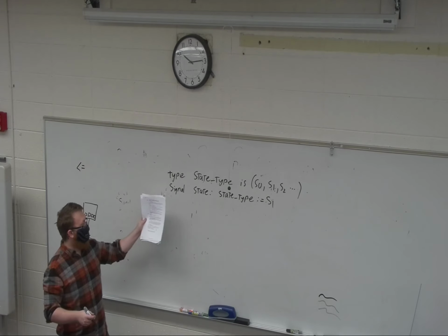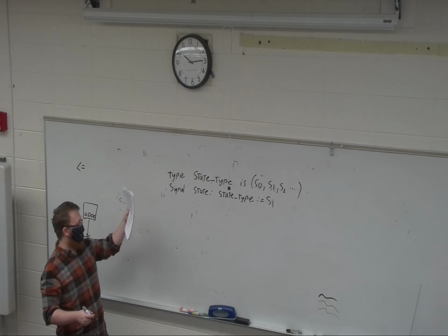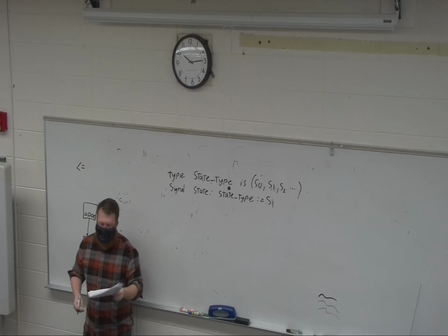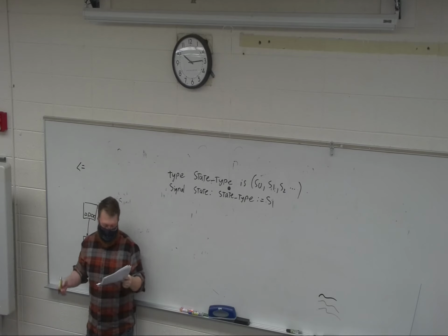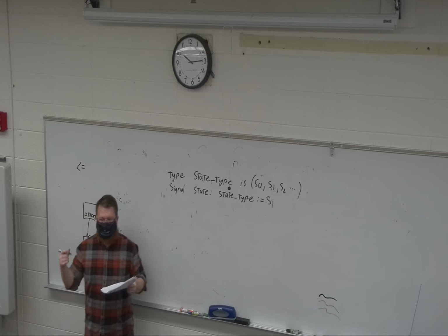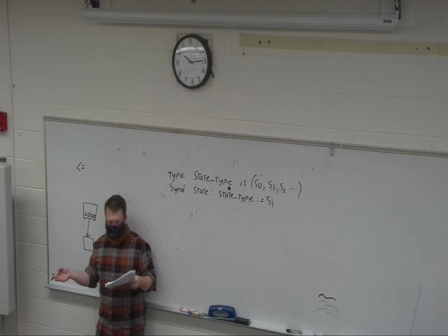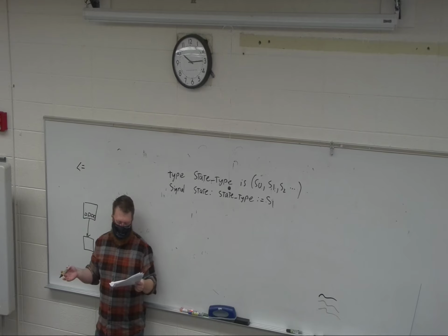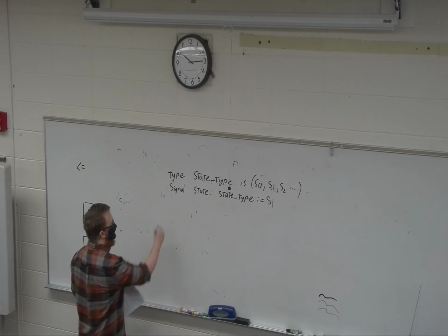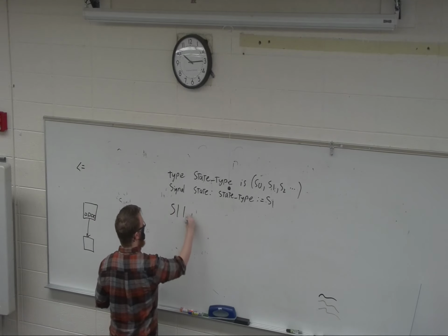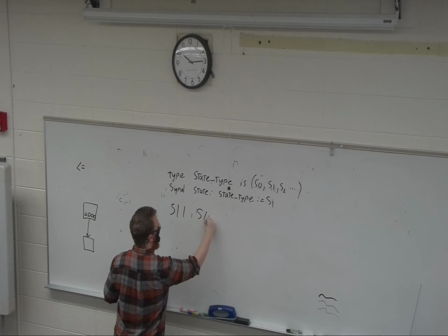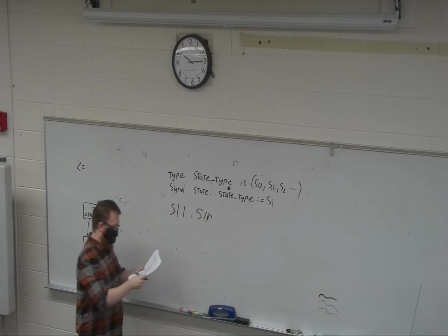I'll circle back around to that after I mention that on page 82, at the bottom, is also a list of VHDL operators that you can use, which are AND, OR, NAND, NOR, XOR, right? That's the binary logical operators. Relational operators, which are equal, not equal, greater than, less than. Shift operators, SLL, SRL. We'll get into what they exactly mean.